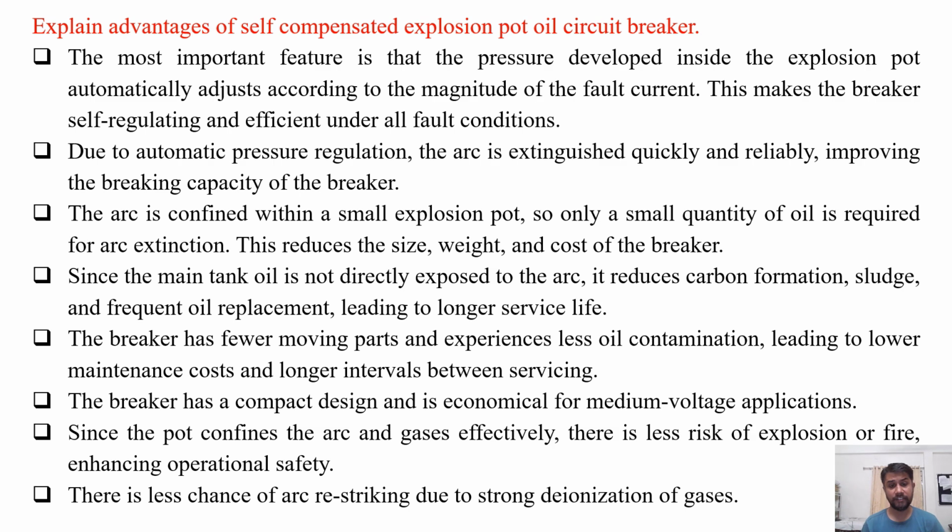Since the pot confines the arc and gases effectively, there is less risk of explosion or fire, enhancing operational safety. There is less chance of arc restriking due to the strong deionization of gases. So these are several advantages of the self-compensated explosion pot oil circuit breaker.